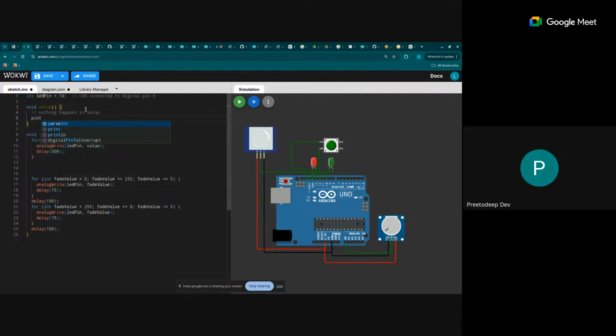Excuse me, sir. Yes. You can share ground pins, right? I mean, different components can share ground pins. That is what you're doing here, I see. Yeah. You can connect as many components to a single ground pin as needed. Ground is always ground, right? You can connect everything to a single ground. No, I see on the analog side, towards the bottom, there are multiple grounds given. I was wondering if there is a special significance of that.